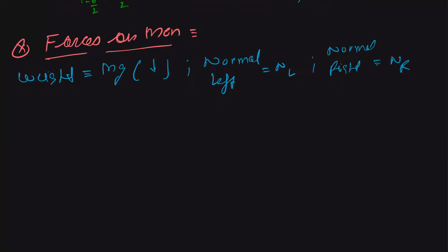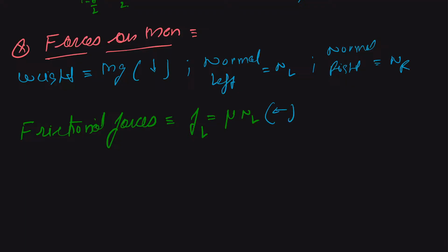We are going to have frictional forces. The frictional force on the left will be FL, which is mu times NL, and its direction will be towards the left, toward the center of the curvature.